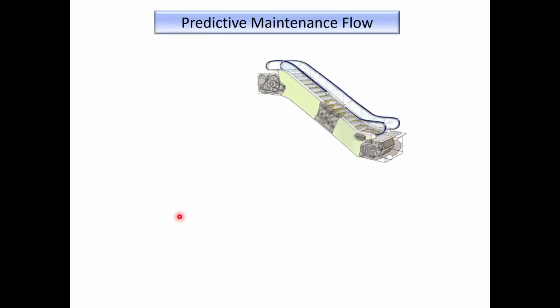We introduced the possibility of predictive maintenance of escalators by constantly monitoring motor current waveform. In today's case, the rule of thumb is that the signs of abnormality are pronounced in the motor current, so predictive maintenance can be performed only on the current waveform.